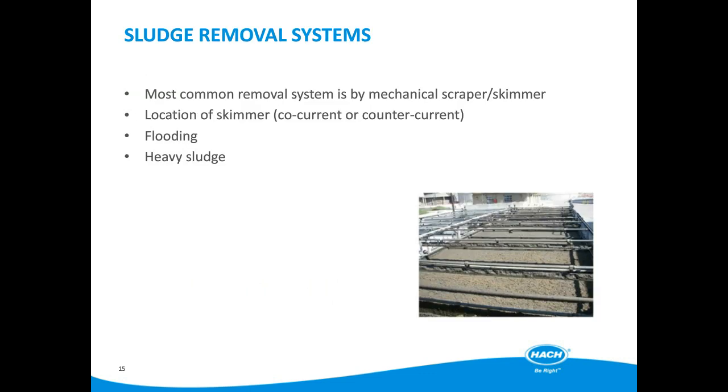Once the floc and particles have been floated to the surface, the floating sludge layer is then removed by physical scraping or skimming off of the buoyant sludge into a hopper. The removal direction is usually in the direction of water flow through the tank.